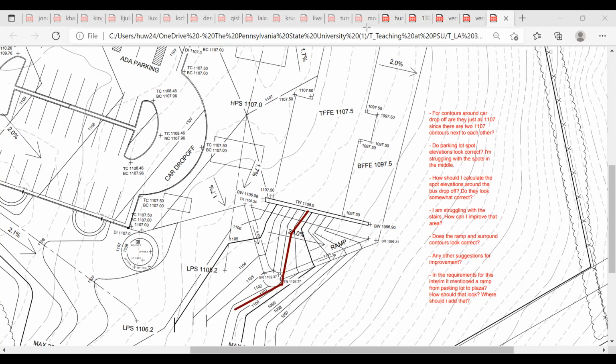It's okay for you to, well, let's see. If you have enough, no, may have enough space or not. Okay, if not, then we need to move it out of the paved or the ramp area and then just turn it around like this. No, 10 will just need to accommodate and do this. So moving the set, because you may not have enough room or enough length here to create that 5% slope. That's why I'm trying to move that out.